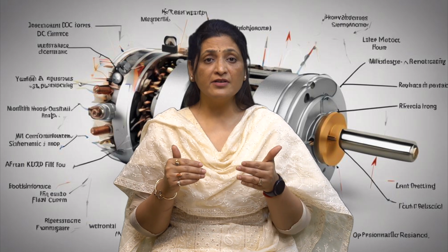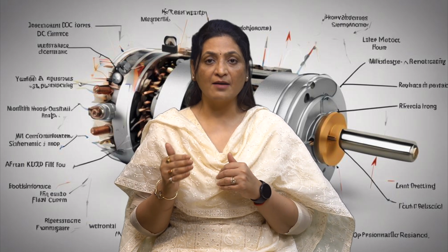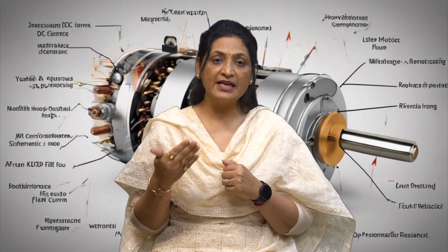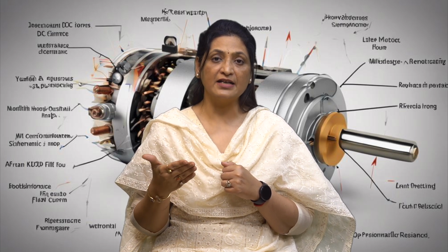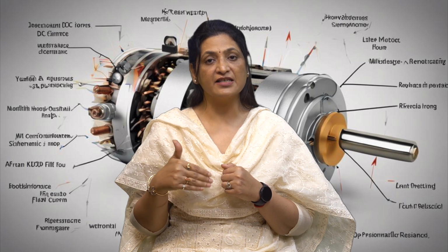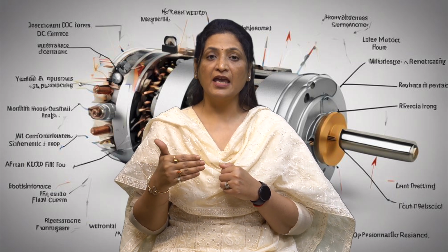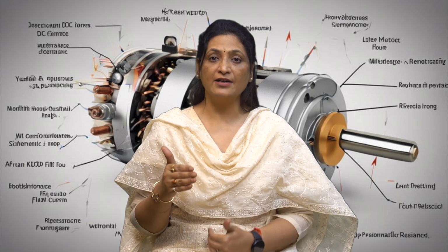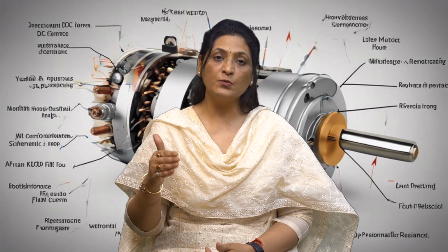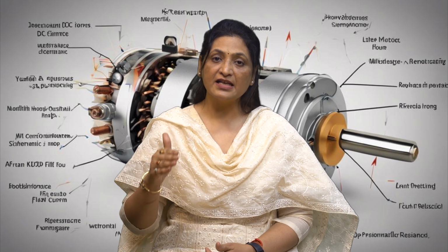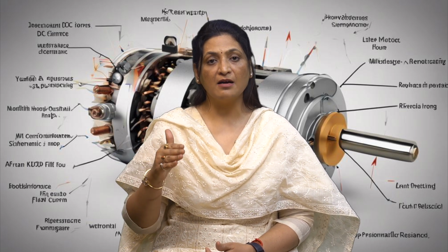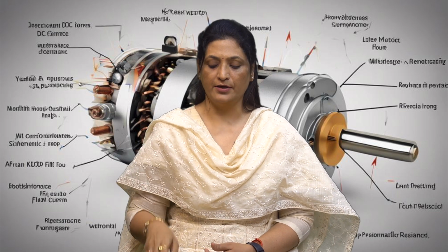Whereas if the drop in terminal voltage Vt due to armature reaction and other drops is much less than the increase in Vt due to increase in flux, then the generator is called overcompounded and its characteristic is rising in nature. If the effects of the two are such that on full load current, Vt is the same as the no load induced EMF, that is, the effects are neutralizing each other, then the generator is called flat compounded or level compounded.